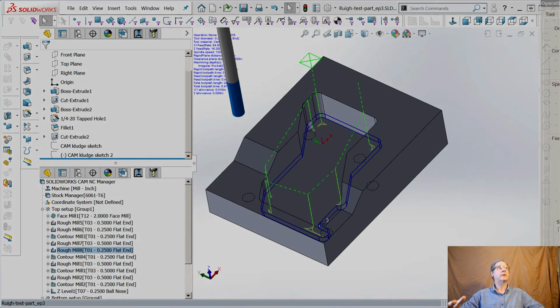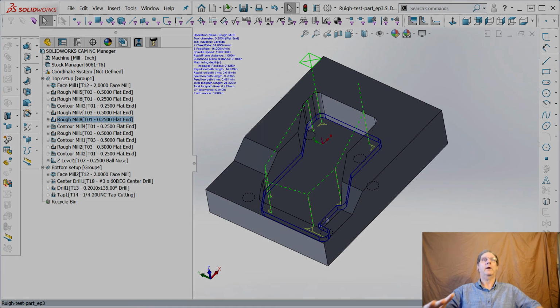So we're going to mess with the speeds and feeds and kind of do a sanity check. We'll see what they guessed with their technology database versus what the HSM Advisor online calculator tells us, versus what Destiny Tool in San Jose says, who I have no relationship with. I just heard about them in a forum, asked my buddies, and they said they used to be on Aldo, now they're in Morgan Hill. He thinks the world of them. They got some of these Viper end mills that they say, surface feet per minute, fast as a spindle will go. If you're aggressive, conservative, they're like 1,400 feet per minute. So we'll get into that.